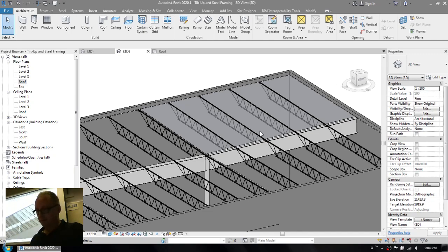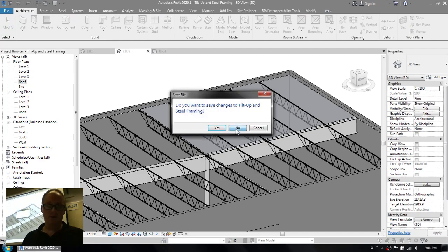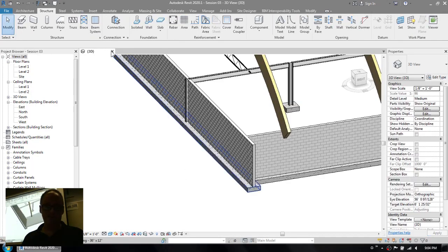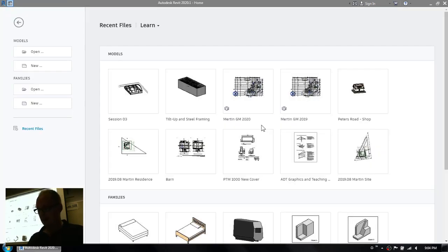Now, last page, page 7 here, we talked about levels of detail and all that good stuff, so that's all fine. What we're going to do now is go through this wood frame exercise, and show how to work with the structural tools for doing sort of an expressive wood structure, and talk about some ways of drawing things like timber beams to work with the planes of a roof.